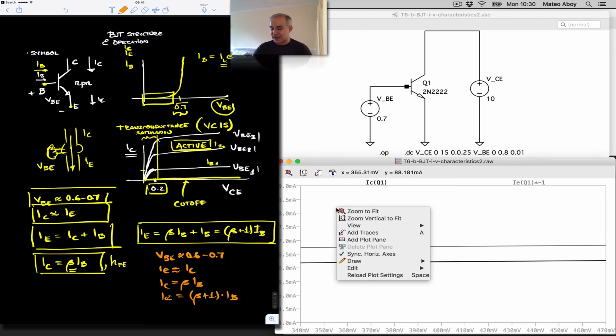Now when we are doing circuit analysis, beta changes so much for the same transistor type in mass production, as well as changes with the collector current, as well as changes with temperature, that this beta and beta plus 1, it is not a good idea to be that precise in your calculations. So I typically will just use this simpler model, and then you simulate. Also, we need to do circuit design that is as much as possible independent of beta.